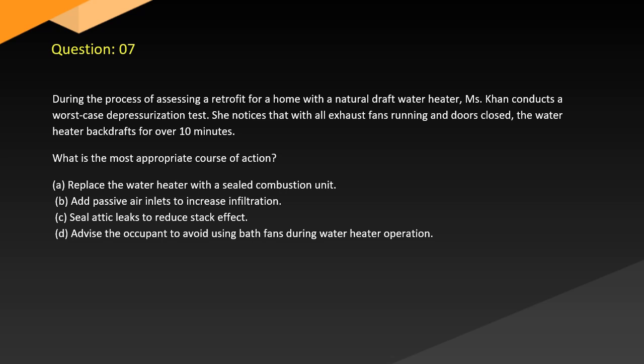Question 7. During the process of assessing a retrofit for a home with a natural draft water heater, she conducts a worst-case depressurization test. She notices that with all exhaust fans running and doors closed, the water heater backdrafts for over 10 minutes. What is the most appropriate course of action? A. Replace the water heater with a sealed combustion unit. B. Add passive air inlets to increase infiltration. C. Seal attic leaks to reduce stack effect. D. Advise the occupant to avoid using bath fans during water heater operation.